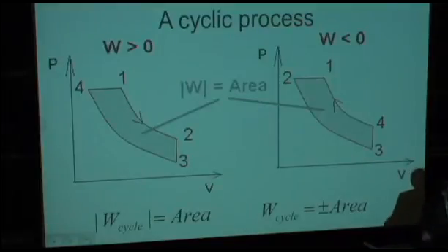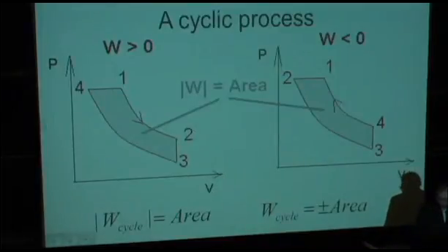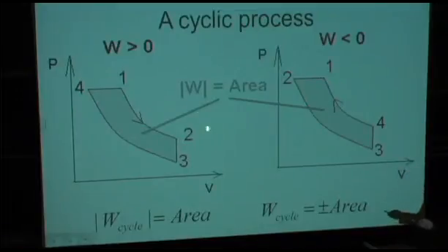Well, as we said, every engine operates in cycles. So it repeats the same cycle again and again and again. It starts from some initial state, and then, well, there are many, many different cycles. This engine has a name, a Stirling engine. That's also a name of a physicist who developed it. It has a Stirling cycle. There's a Carnot cycle, Watt cycle, many different cycles. And for each cycle, you see, when volume expands, positive work is done. When volume contracts, negative work is done. So the total amount of work will be equal to the area of this cycle.